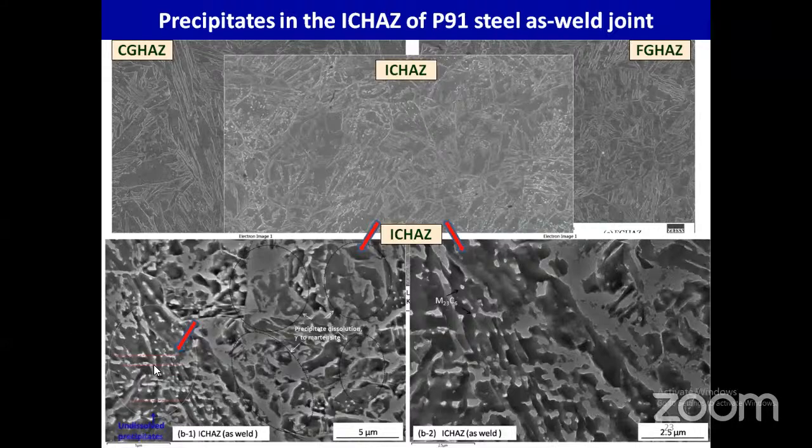It's about 70 nanometer. Since the precipitate exists but the matrix transformed to austenite while heating, and while cooling fresh martensite forms, in the process we lost the precipitate strengthening. Here we can closely see that the precipitates decorated along the boundaries were lost because of transformation to austenite during heating. While it's cooling, the boundaries form in different locations. If the precipitates are decorated along the boundaries, only then will we get more benefit rather than at the other locations.